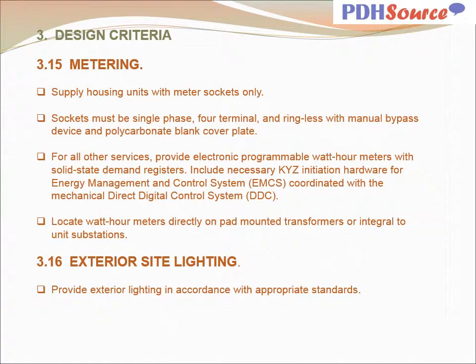Supply housing units with meter sockets only. Sockets must be single-phase 4-terminal and ringless with manual bypass device and polycarbonate blank cover plate.